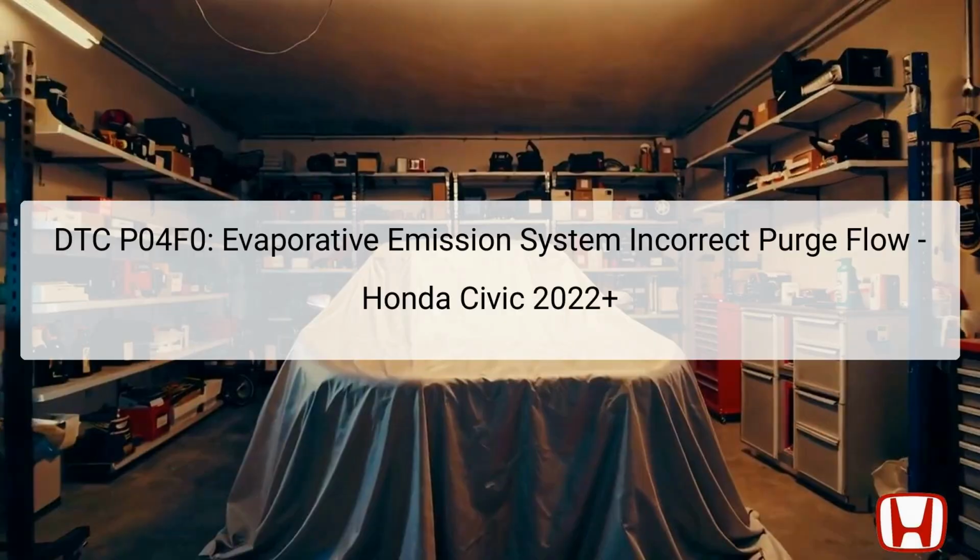The Diagnostic Trouble Code, DTC P04F0, relates to an issue within the Evaporative Emission (EVAP) system of the Honda Civic 2022 and newer models. This code indicates that the Powertrain Control Module, PCM, has detected an incorrect purge flow associated with the EVAP system. The purpose of the EVAP system is to prevent fuel vapors from escaping into the atmosphere, thereby reducing emissions and improving environmental safety.